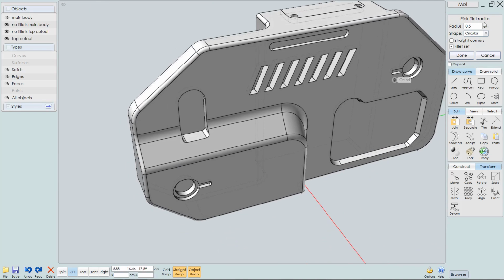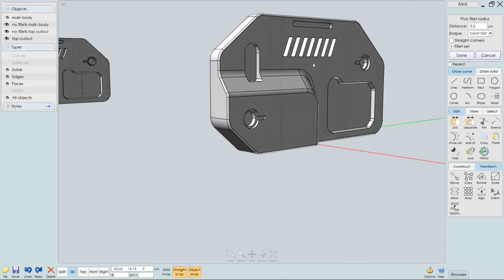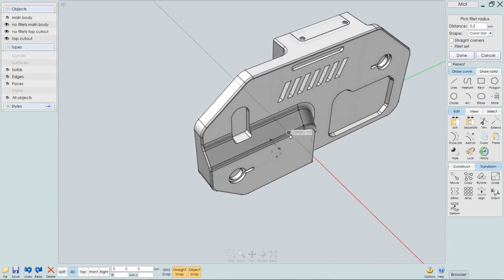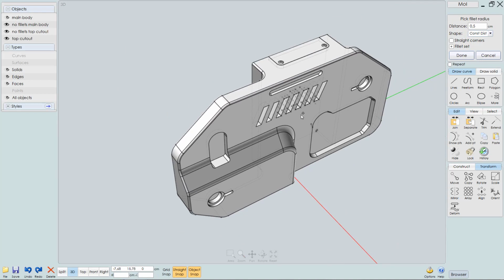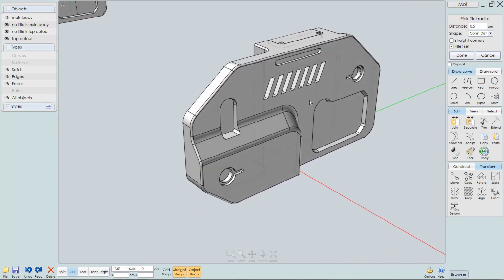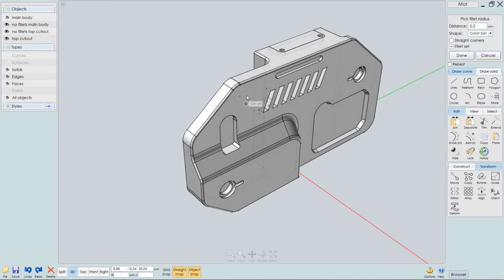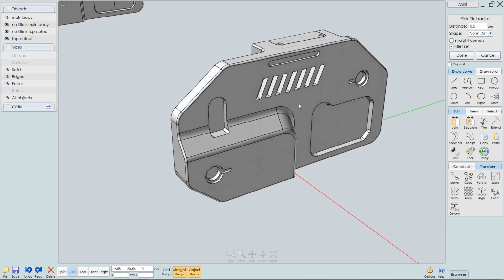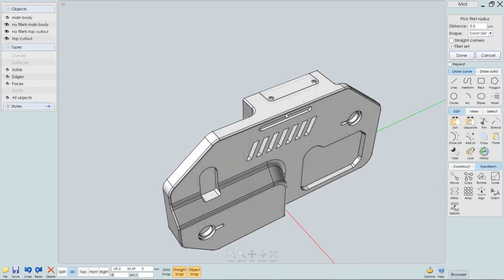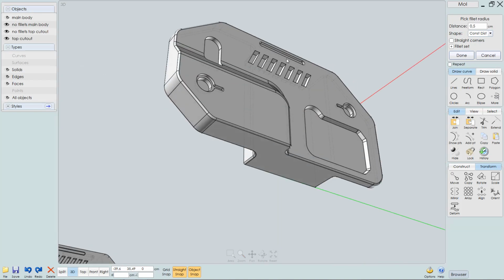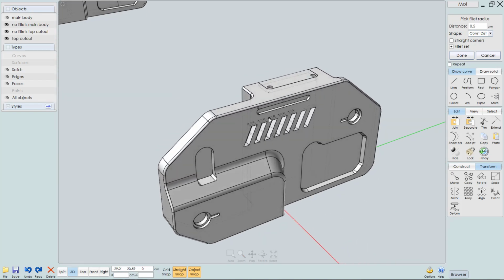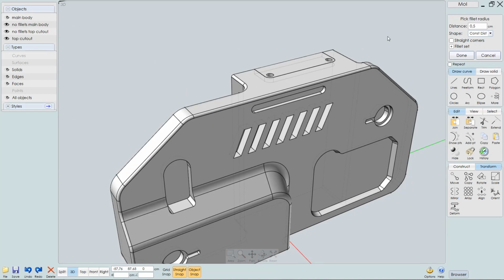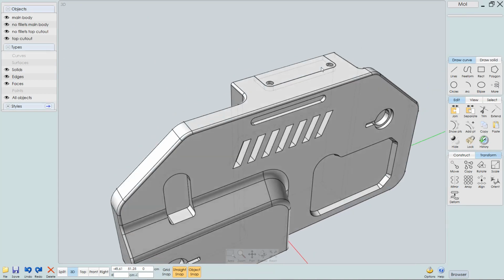Let's try constant distance. I think I'll stick with that because I find that the objects I export from MoI and import into Cinema 4D tend to look not quite as round as they do in Moment of Inspiration. So I'd rather go with bigger fillets in MoI because I think those will look better in Cinema 4D. So let's confirm,